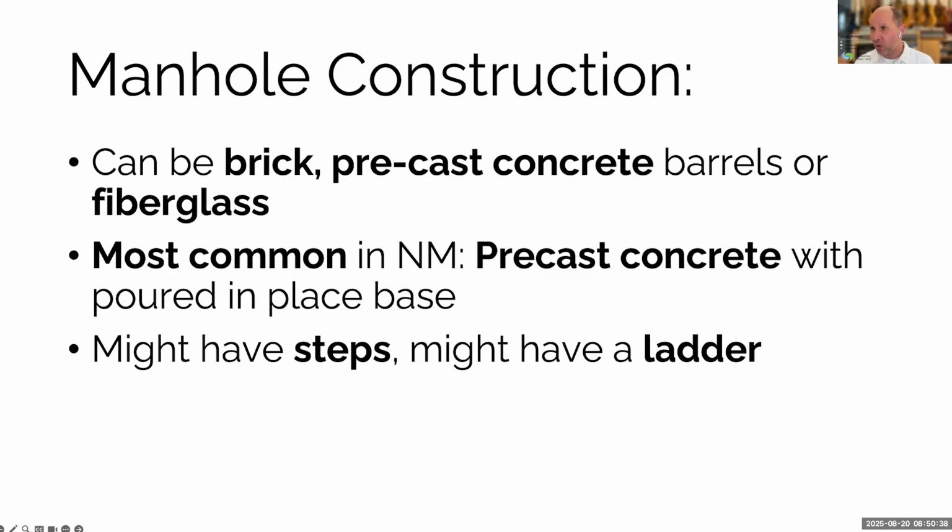So they basically excavate the hole, they pour the base, and then they just bring in these precast, pre-made cylinders and stack them up to the appropriate height. Typically, you're going to have steps or a ladder to get into them. I'll show you a diagram in a second.